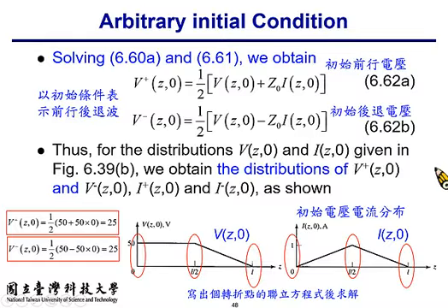We know that some part of the signal goes to the right and some part goes to the left. And because the two ends are terminated with open circuit, they will get reflected. So things will continue going on within the transmission line. Right? And we would like to know what happens with the total voltage and total current on the transmission line after a certain amount of time. Okay?